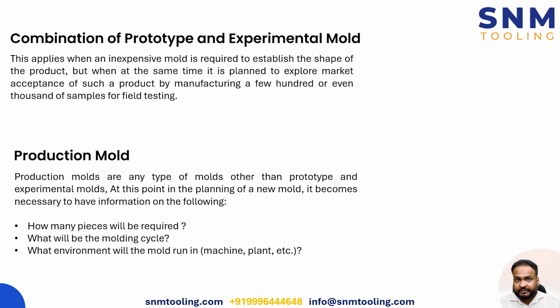Dimensional inspections and layout reports can be done, and then we can get to know how the product is behaving, whether the dimensions are repeating and consistent throughout the sample set of products, whether they are within specification, or varying a lot, or coming out of tolerance, right?